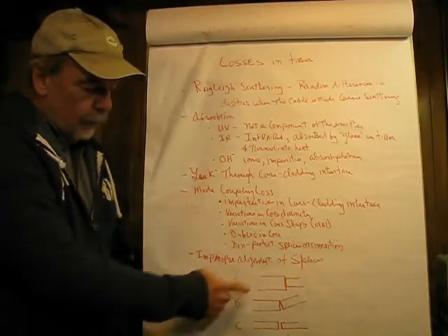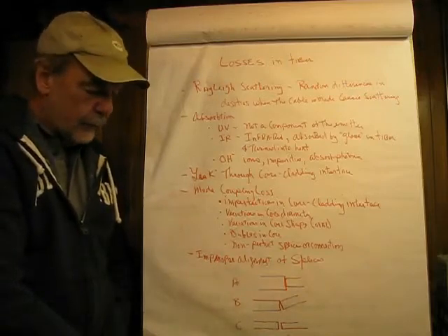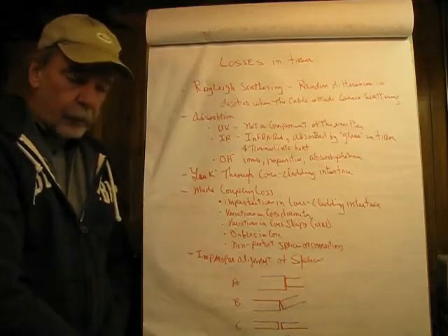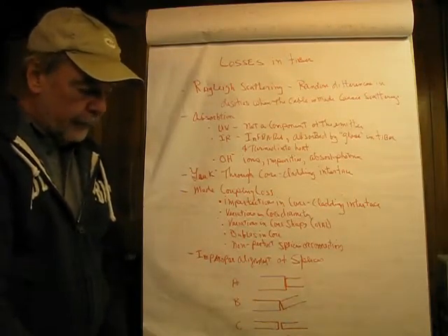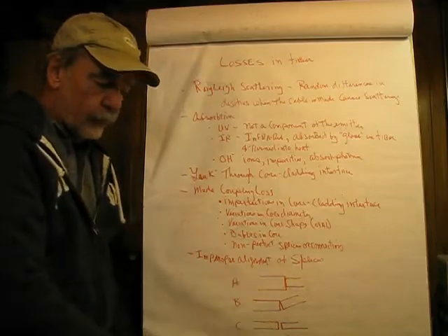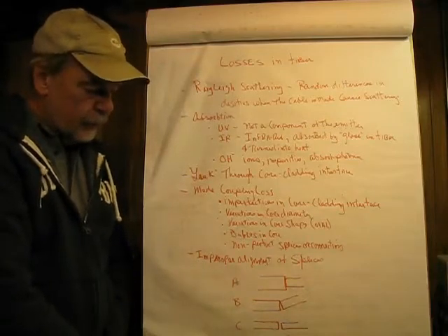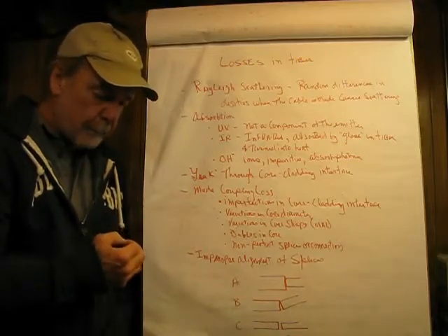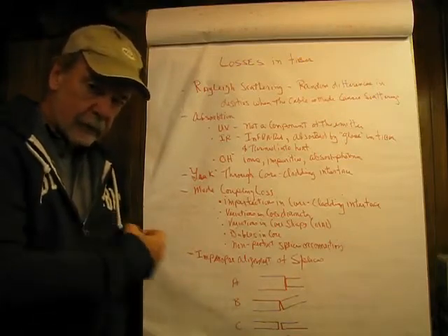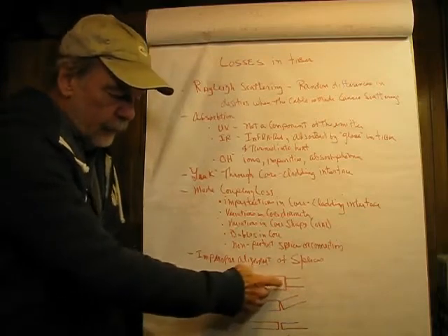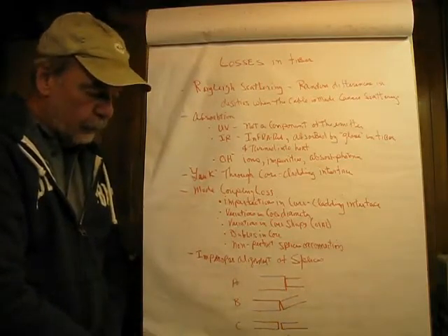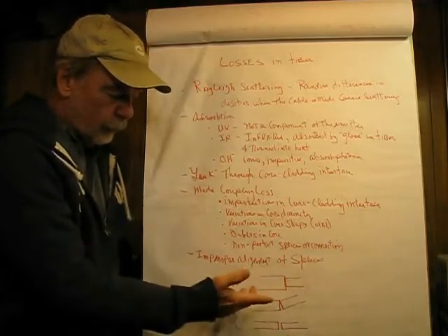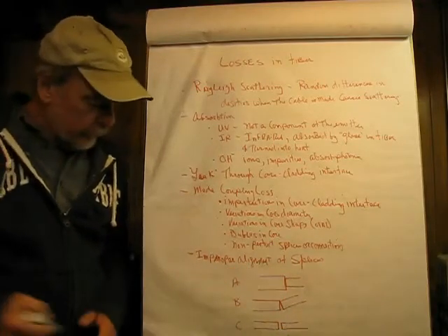Now the way these cables are spliced together is that there's a van on a pickup truck, and the cable is pulled out of a manhole and brought into the van and put in an instrument that has a set of mirrors. So what a technician would do on the individual strand, after it's been identified by the color and stripped of the protective coating, is put the ends of the fiber into this device, and then they look at it, say from the side, and line this up. Of course it would be ideally like this.